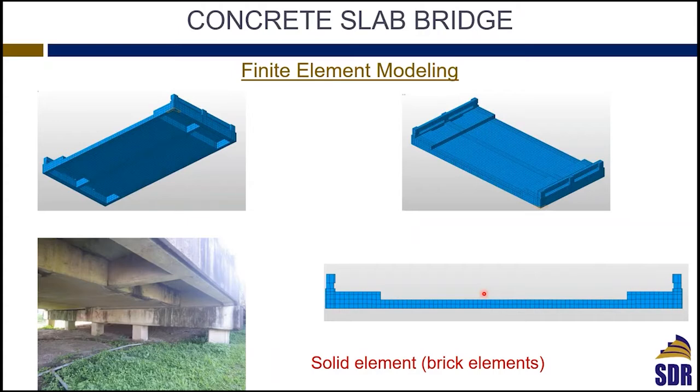Typically for the slab spans, we model them using brick elements or solid elements. Yes, modeling using solid elements is a little bit more complicated or more sophisticated than modeling with shell elements or frame elements, but that's the only way you can capture the behavior of the bridge, given the fact that you have the slab, the roadway, then you have, I'm pointing here to the sidewalk, which is elevated here, and they had these kinds of diaphragms that were supporting the sidewalks. And then the slab at the end is supported on the pile bent.